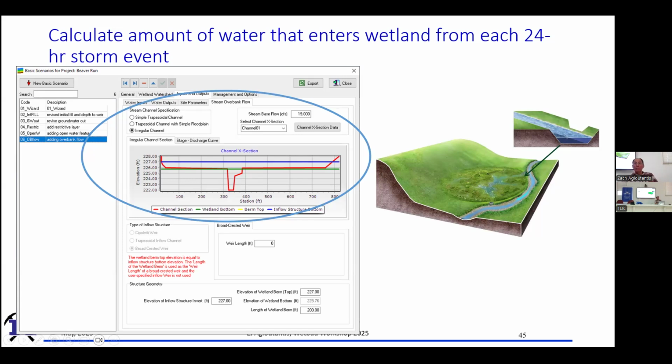So this is a cross section of this area right here, an input weir. This is the input weir, and we can actually model that as a cross section there. The water from the channel, from the stream, we calculate the flow, and then that flow is going to get into the inflow weir. Again, we'll measure how much that's going to get filled, and we can calculate how much water we get into the wetland. This is all water balance, but it's restricted by the specific geometry of every channel that we have.